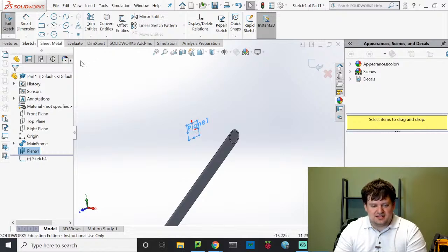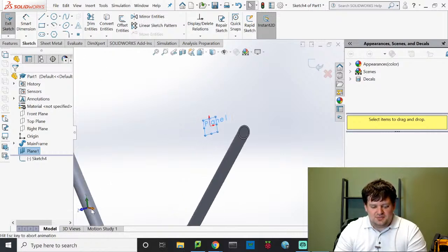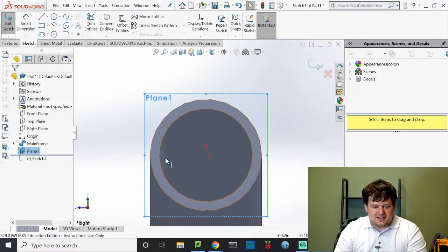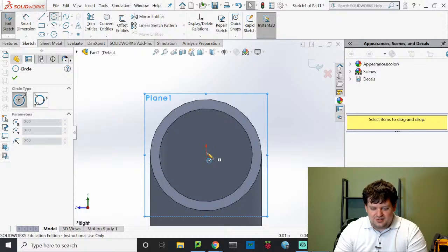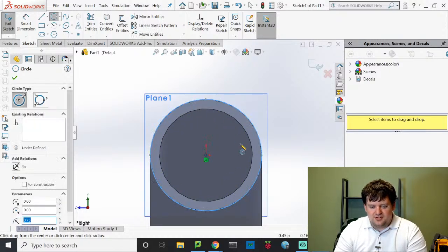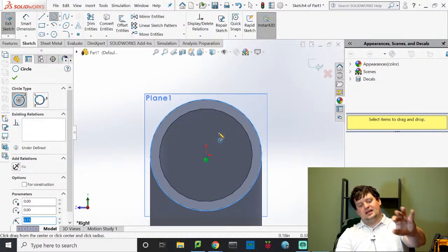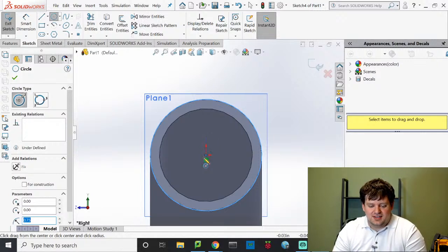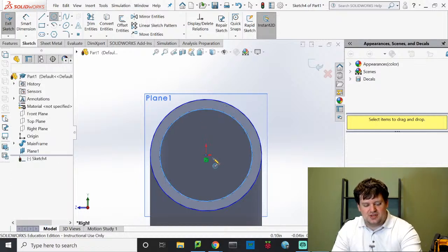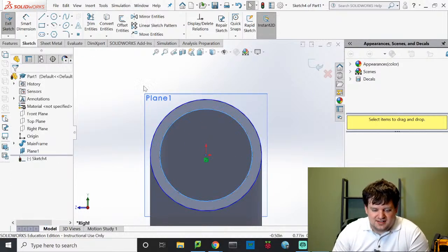I already had that plane selected. I click sketch. I am now currently sketching on that plane. Now I'm going to draw the same profile as I did right here. I'll use the same origin. You can even draw lines projected on here because I'm looking down the x-axis onto this. Everything is a projection, and SolidWorks sees that and actually allows me to pick these points really nicely.